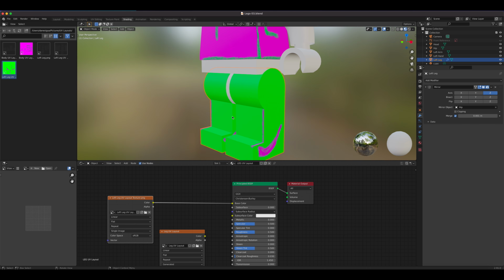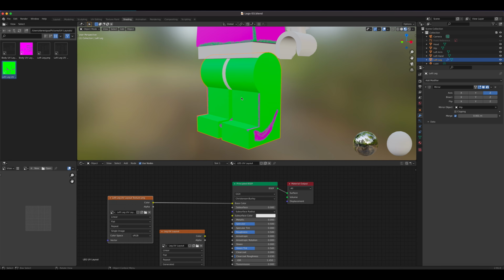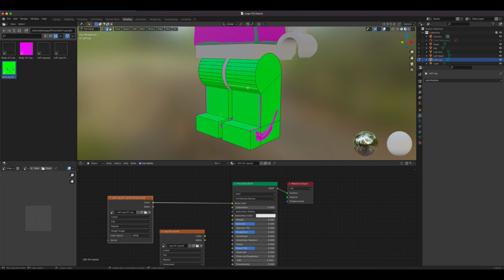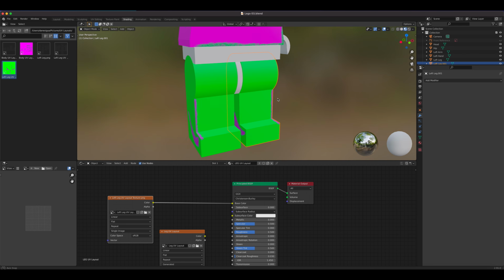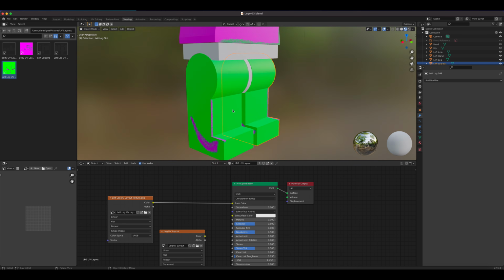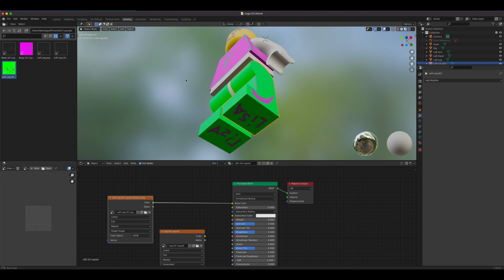And then when you plan to animate them, you want them separate. Of course, you can apply the modifier and then go to your selection. Like if I select the whole thing here, press P. We'll have a lesson on this. I just want to show real quick that it can be done like this. And you separate that, and then you get 2 independent ones, and you didn't have to do any UV on this one. Everything kind of matches. All right, there you go.